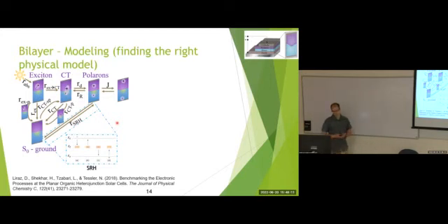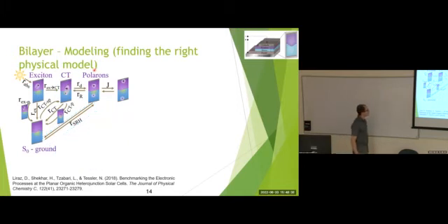And we were very glad to find that this is the process here, because it seems that the SRH traps are not directly related to the charge generation. Which means that maybe with a smart design, one can get rid of these SRH traps with minimal damage to charge generation. Also, I want to emphasize this process here, which is thermal formation of CTs, which is not important at all when we shine light at the device, even at very low light intensities.